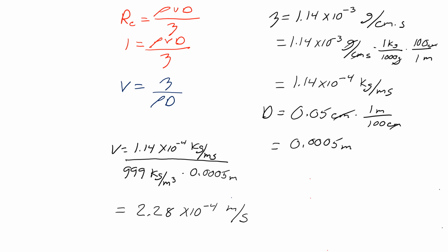So is that a fast velocity? .28 times 10 to the minus fourth meters per second. So it's moving a pretty tiny amount every second, right? But if it moves any faster than that, then Darcy's law wouldn't be valid.